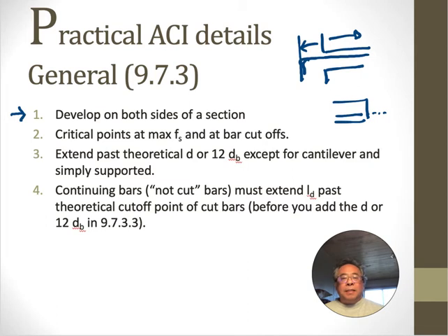And then finally, the continuing bars, the bars that are not cut, must extend LD past the theoretical cutoff point of the cut bars. That's a little hard to explain. I'll make a separate video just for this topic, and so we can talk about that in more detail.